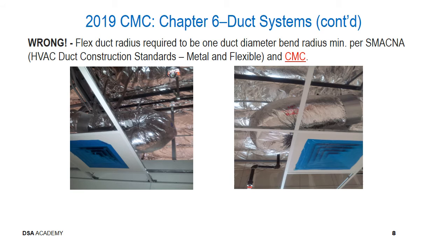This slide shows a couple of images of inappropriately installed flex duct at a register. Obviously, the images on the left and the right are showing situations where the flexible ductwork is certainly pinched off, and the minimum required bend radius has not been maintained.